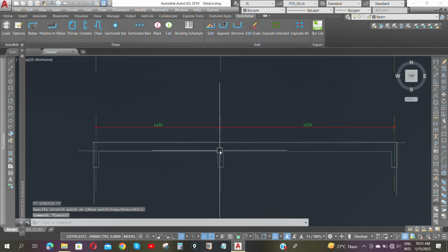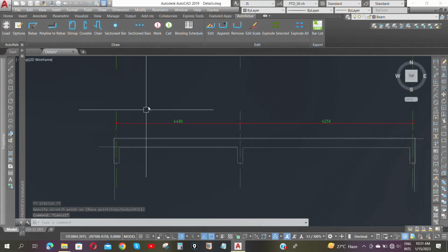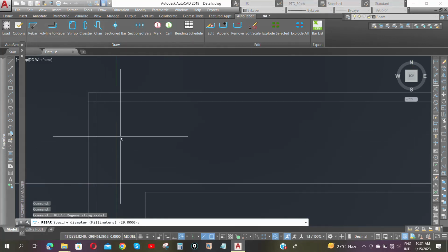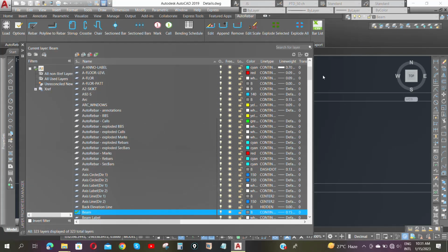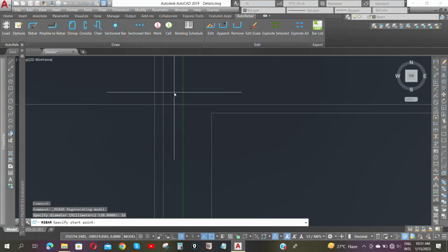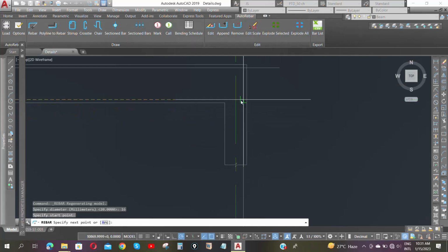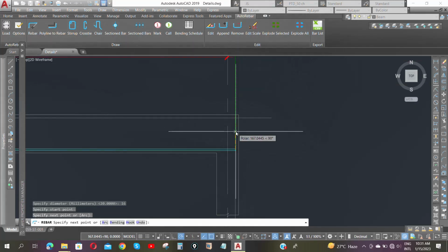To guide my limit, the reinforcement limit, so I can come here. What type of diameter reinforcement do I want to use? Let's assume I'm using 16, so I can type in 16 there. So my development length, let's say 200.